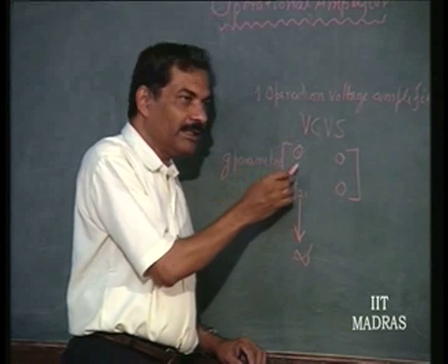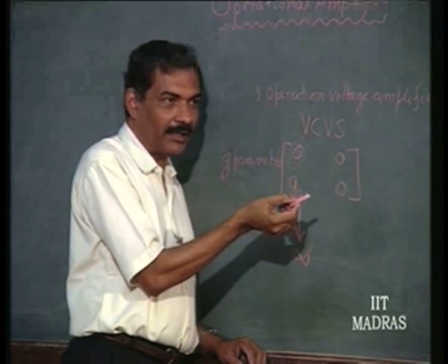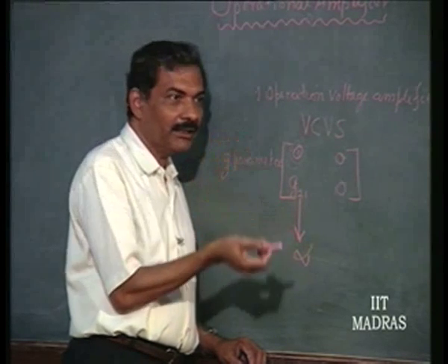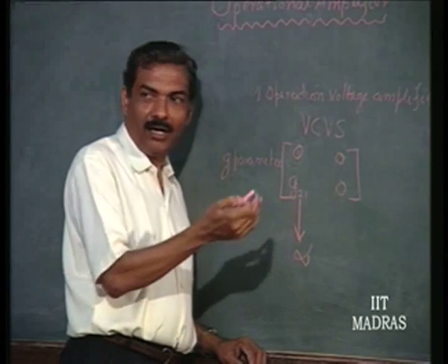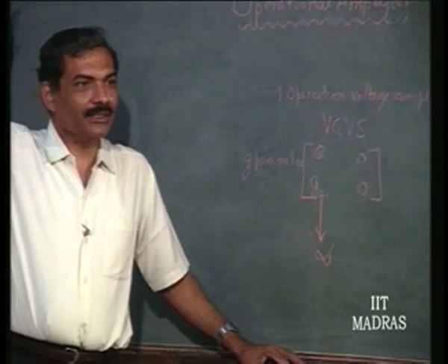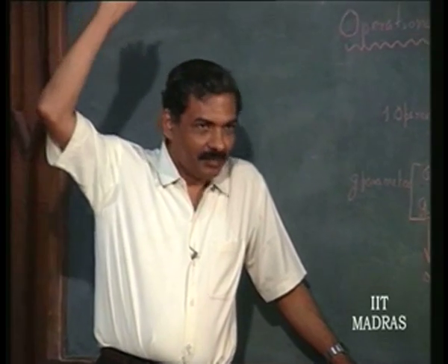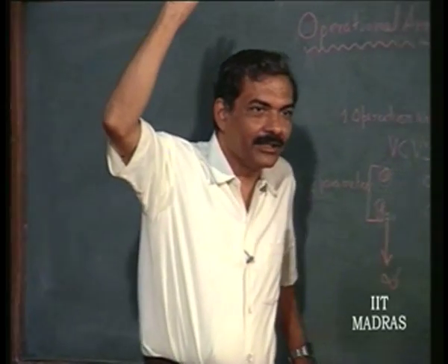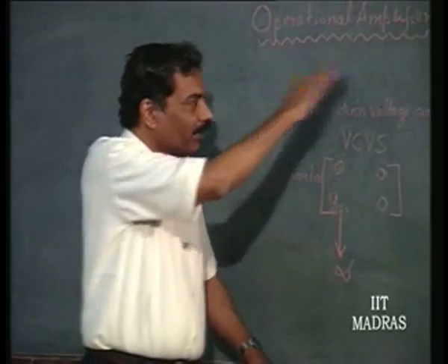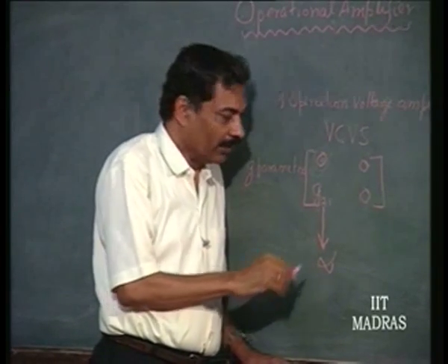So, input impedance increase can be done by using a Darlington pair at the input stage, by using FETs, JFET, by using MOSFET. So, this is the order in which input impedance can be increased, but we have seen the disadvantage of the input impedance increase. Remember that simultaneously offset is going to increase. So, depending upon what application it is going to be used, we will decide whether it is a wise thing to do or not.